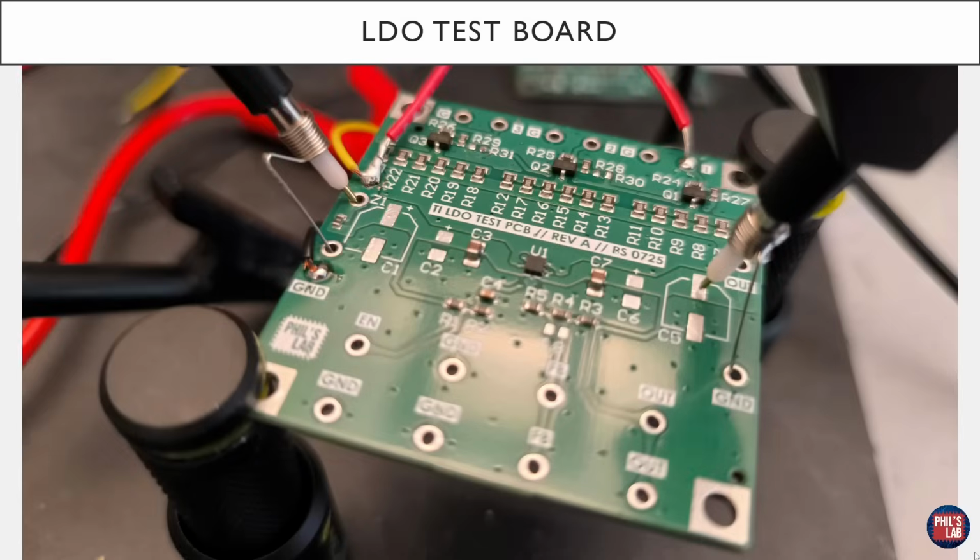In any case, we'll soon be starting to look at some measurements, and for our measurements we'll be using this custom LDO test board, which contains a low dropout linear regulator U1. We have placements for various input capacitors, output capacitors, feedback networks, as well as various loads we can apply to the output for determined output currents. This is a very simple test case that allows us to easily measure the power supply rejection ratio of this particular low dropout linear regulator.